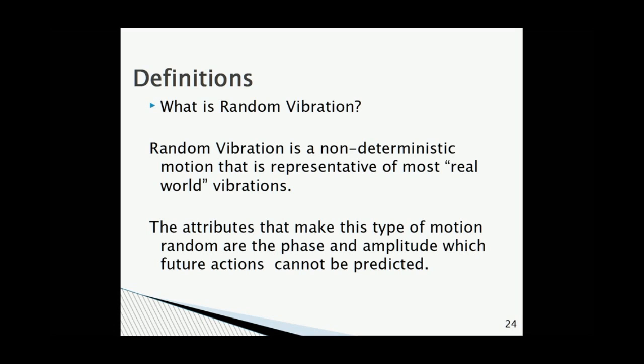Now, going back, I told you that you would appreciate the unit GRMS because RMS expresses magnitude for a varying quantity. And now you see why it's used in random vibration testing, because random vibration testing has content which varies randomly. So GRMS is the unit of measurement you would want to use to express the magnitude of a varying quantity. So now you understand why GRMS is used for random vibration testing.